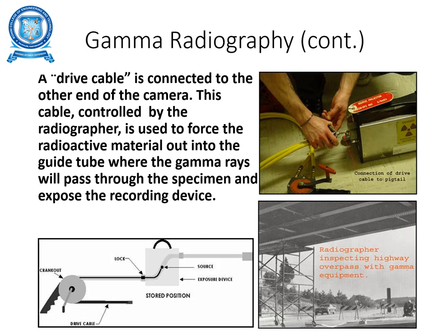So here a drive cable is connected to the other end of the camera. This cable, controlled by the radiographer, is used to force the radioactive material out into the guide tube, where the gamma rays will pass through the specimen and expose the recording device.